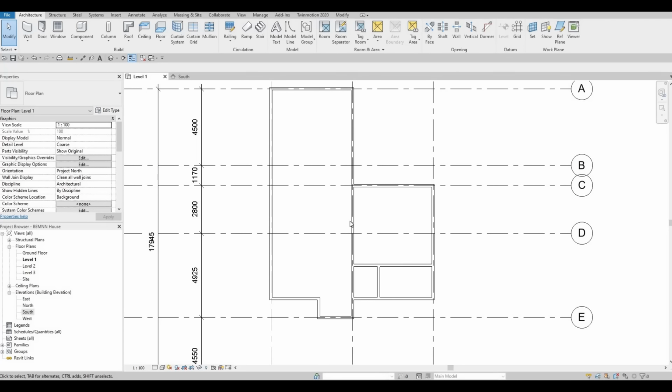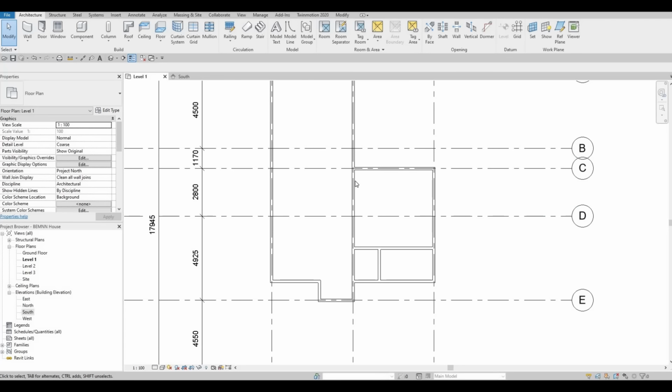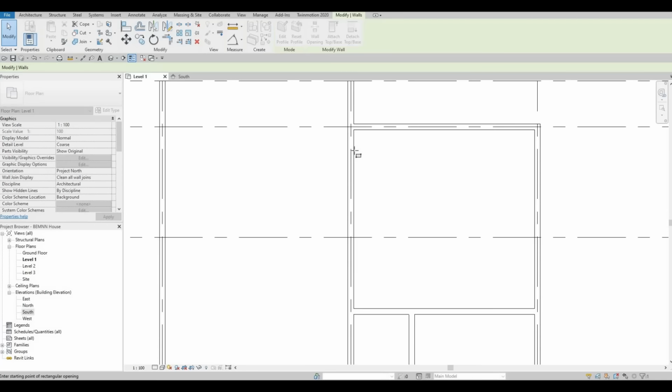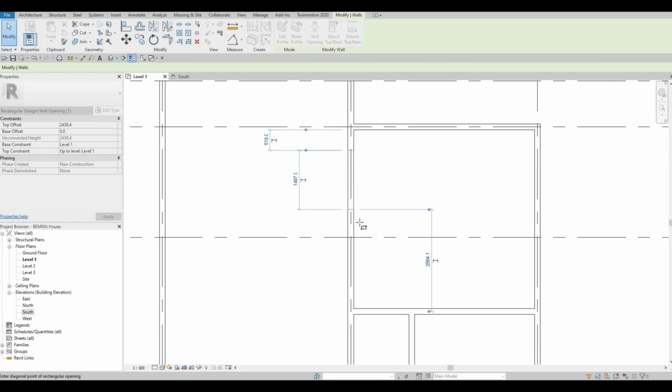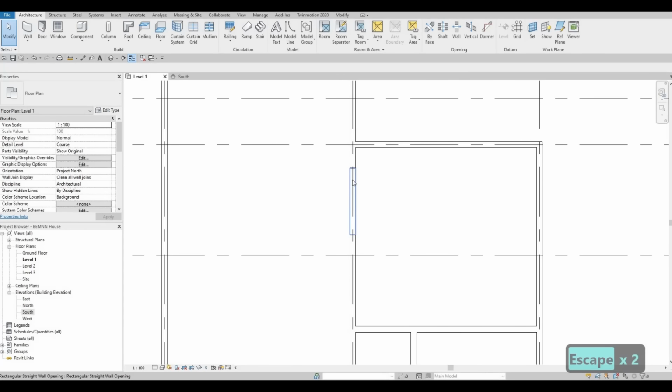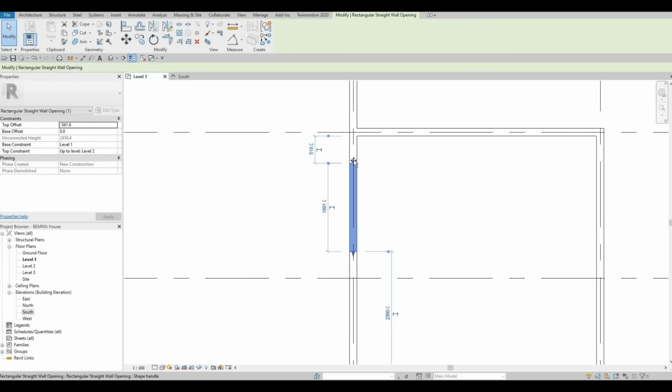And then here, what we could do is we could select this. So once you select that, we're gonna create a wall opening. Select this wall opening, and then here, select the wall, when it will start and when will it close. So now, as you can see, once you hover here into your crosshair or mouse crosshair, you can even select that, and then you can grab it and you can extend whatever you want.